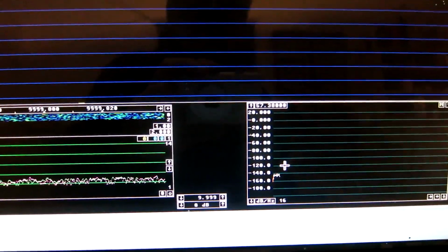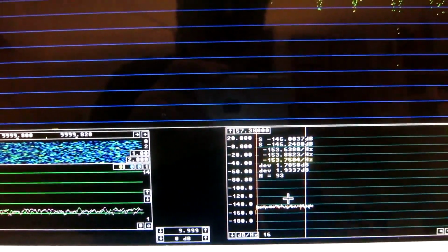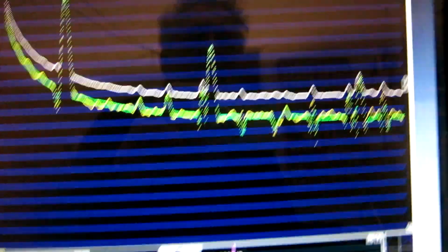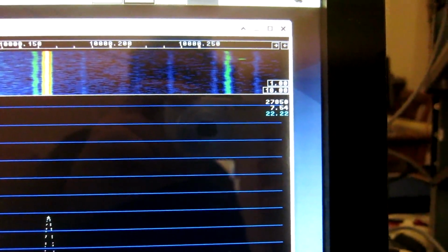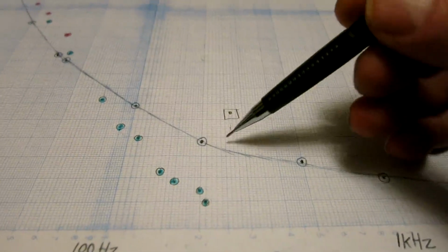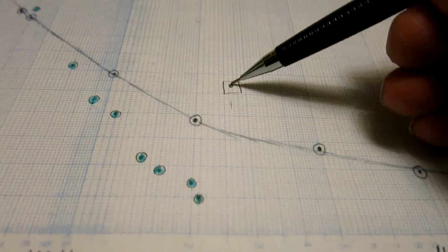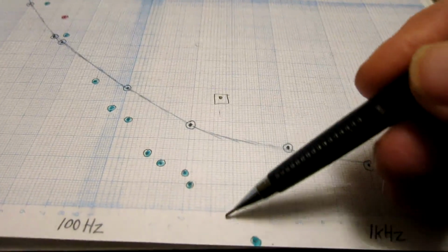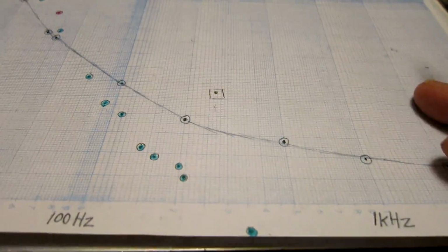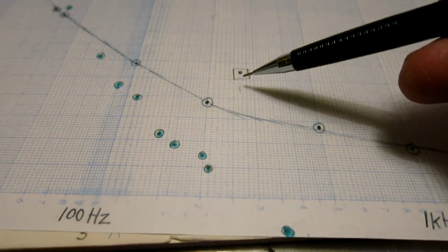And I wait for the noise floor. The noise floor is here, minus 153.7 dBc per hertz, and with a correlation advantage of 7.5 dB. That is here, 161.2 at 265 hertz. This is about 10 decibels above the line I had when the output amplitude was limited by the diodes and the resistor.